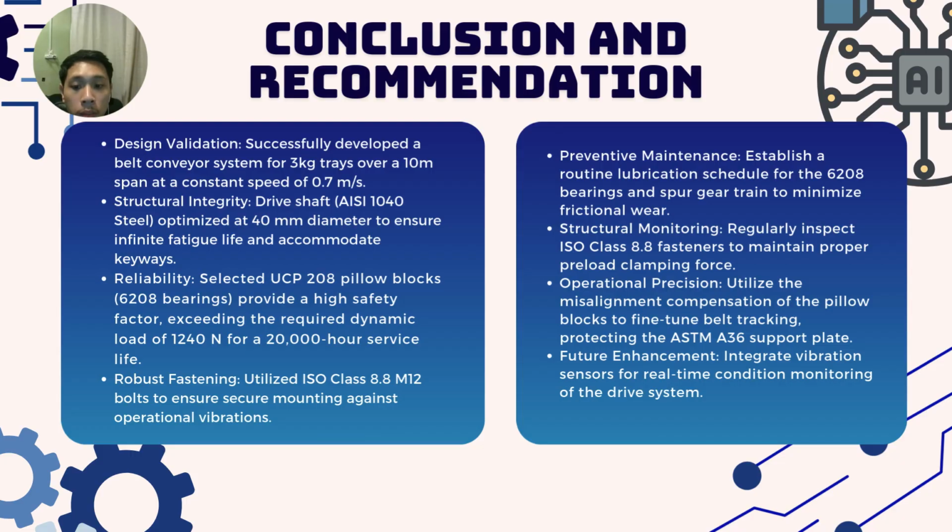For the recommendation, to maintain this performance, we recommend three simple steps. For the first one, we recommend establishing a monthly lubrication schedule for the bearing and gear train. The second one, perform regular torque checks on the mounting bolts to ensure the preload remains intact. And finally, utilize the self-aligning features of the pillow blocks for periodic belt tracking adjustment to prevent uneven wear. With these measures, the conveyor is ready for long-term